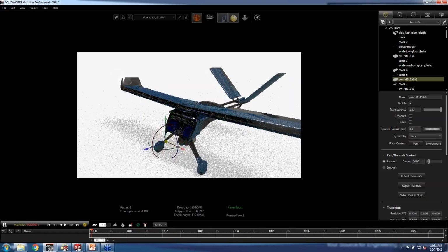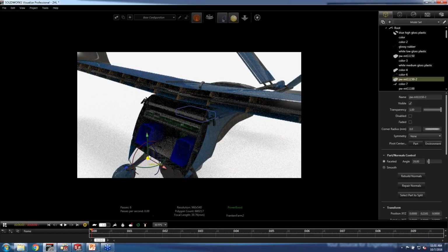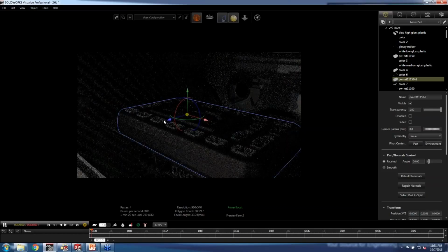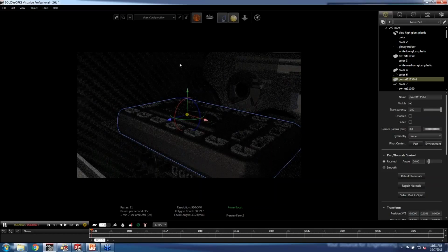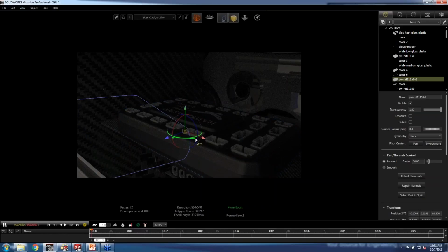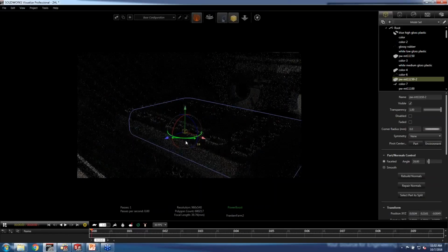And so now if I take this pivot point, I can just move it to the model, and I'm assured that it's actually snapping to the model, which in the past you'd want to grab these things, move them around and change the angle, maybe do 4 viewports so you can see top, front, right, and then try to move it around. It's really difficult. Well, now you just move it and it's going to snap to the model, so we'll snap it there, and let's go ahead and now rotate that part along that pivot, something like that.